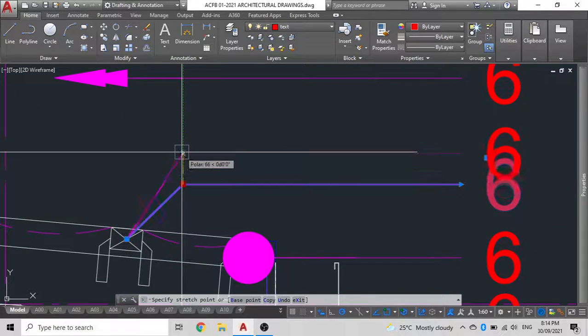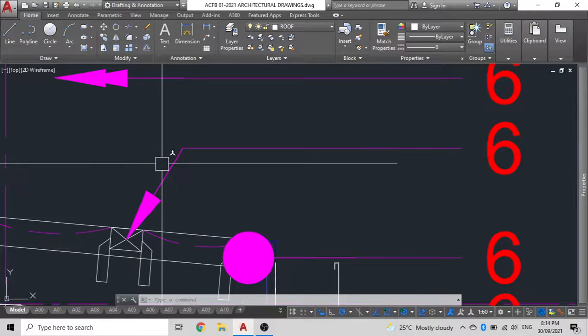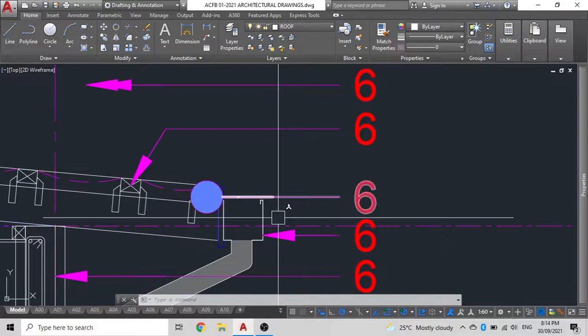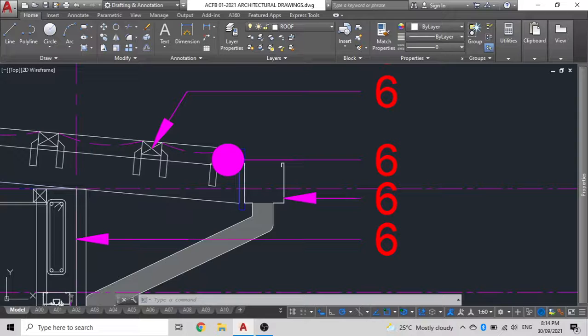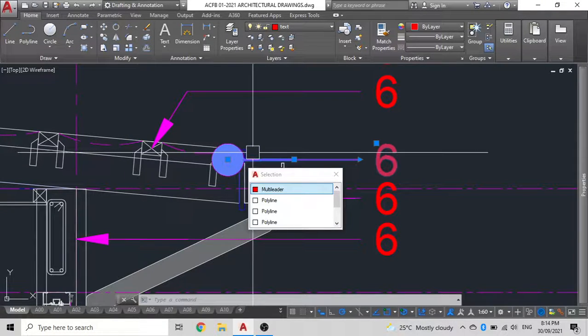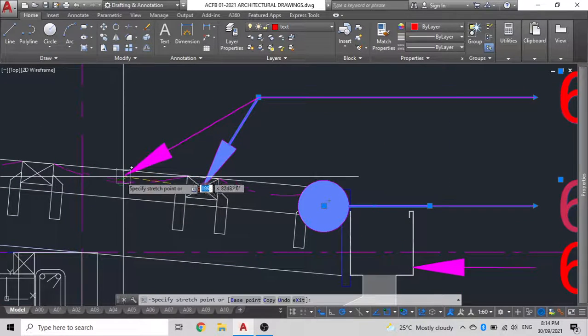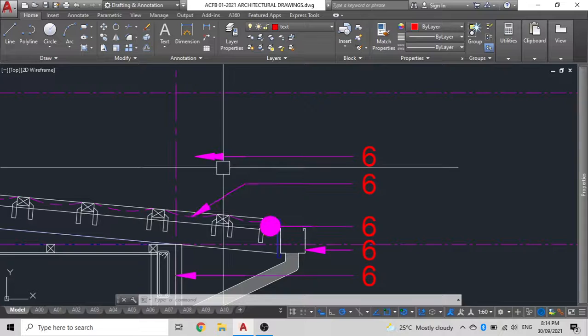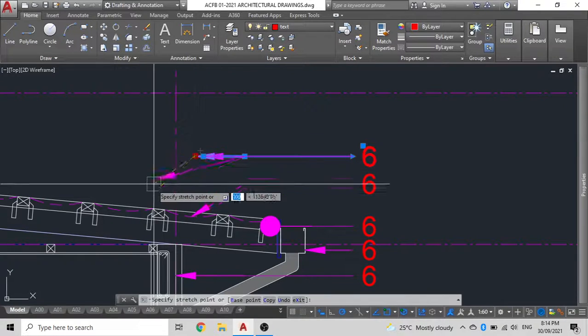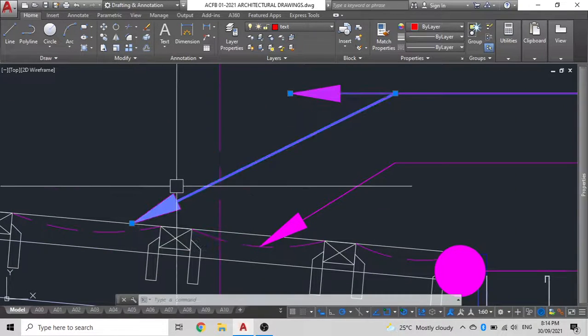And then you just pull your leader to the top. So you're basically pointing at a gutter over here. Then you're pointing at a 3x2, a 75 by 50 purlin over here. Then you're pointing at an insulation paper over here like so. And after that, you're pointing at the roof cladding, sorry, like so.